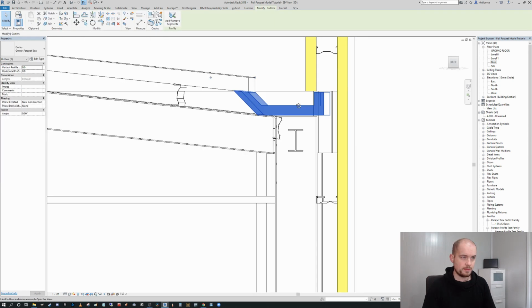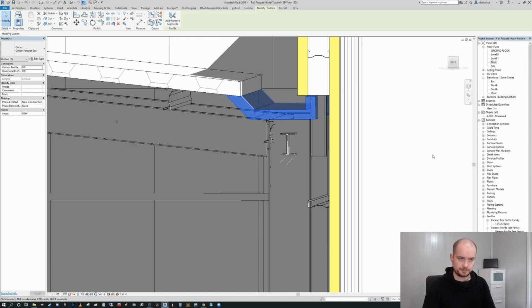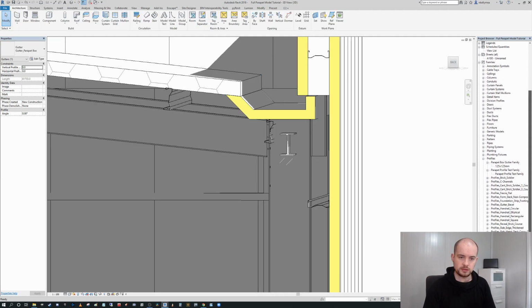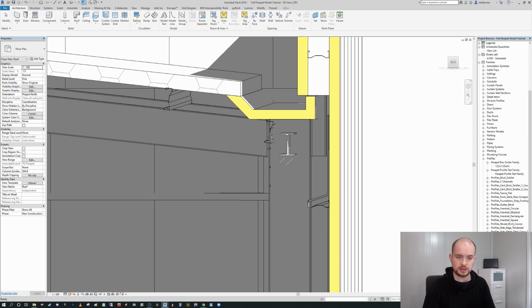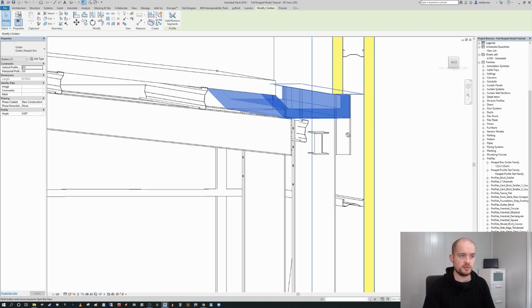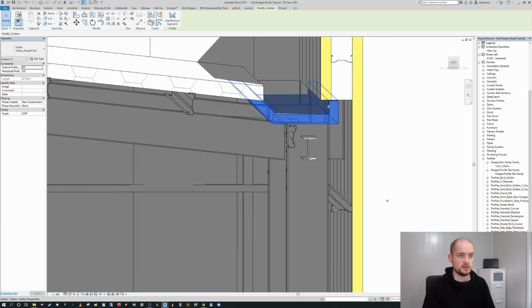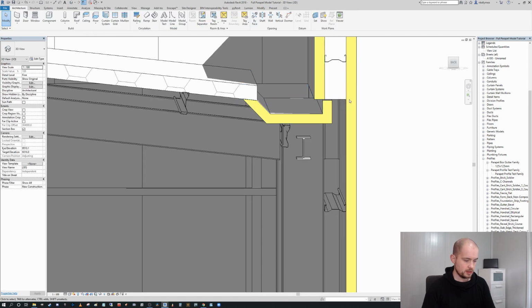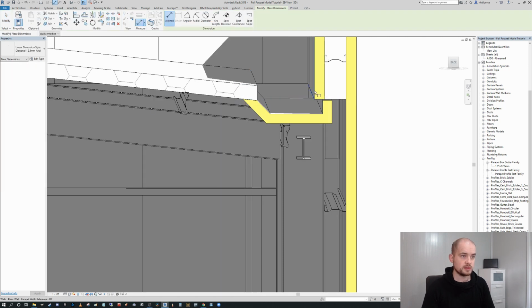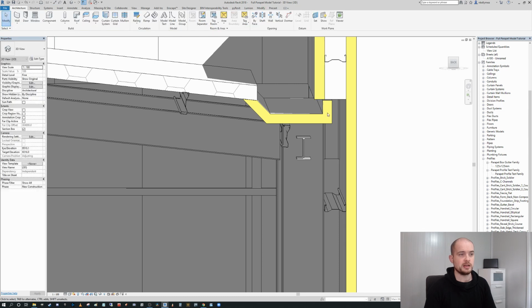So I suppose the first thing we need to do is go down to our gutter profile itself and start making edits to the profile reporting values so that it works in this context. I'm going to press DI here, just very quickly in 3D, and measure the distance between these two. So our gutter, I think, needs to reduce. It actually doesn't need to reduce. What it needs is an offset value, I think. If I reduce that 50 mil, I think it'll be suitable.